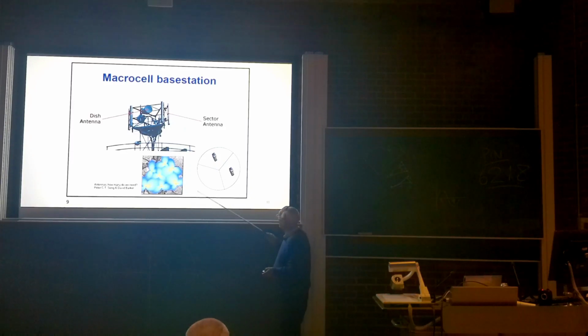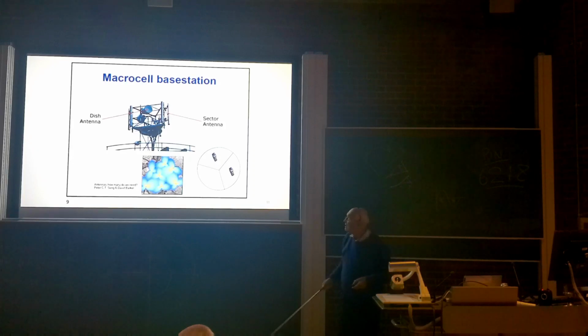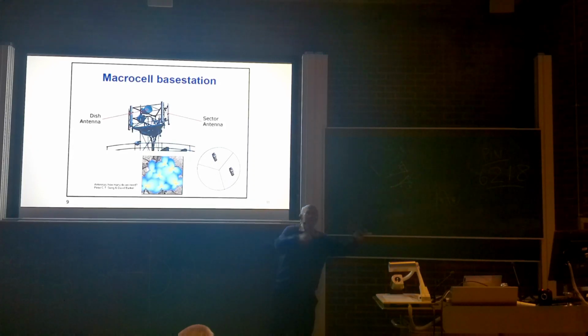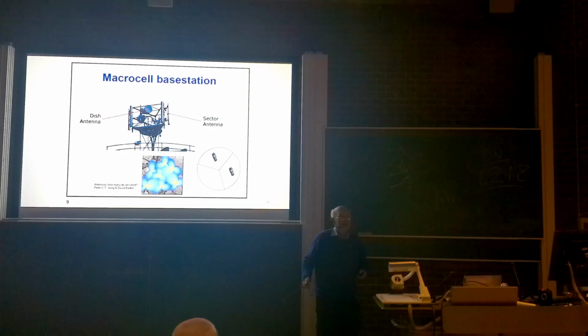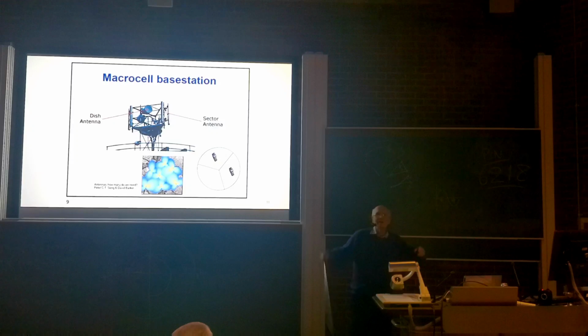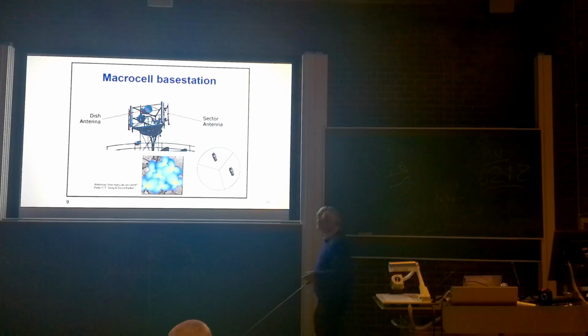And then, of course, the sector antenna has a particular problem in that if a car or a mobile handset moves from one sector to another, you've got all the problem of switching from one sector to the other. You've got that problem as well as moving to a new base station. So it is a complicated system. It's all dynamic, but it's all hidden away, and it's pretty good, I always think.